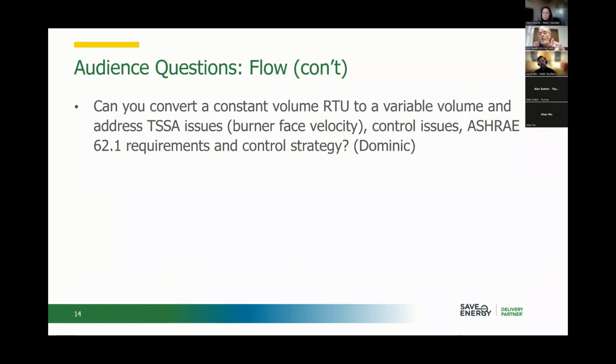There is one point I want to make with this, and that is that you run into a bit of an issue where if you're looking at how much air you need to move in from purely a temperature perspective, that's one thing. But the other thing you have to keep in mind, and this is the issue with any kind of ventilation where it's occupants that you're trying to make comfortable, is that diffusers are above our head at the ceiling, and that air has to get down to the occupant. And if you start reducing the velocity of that air as it leaves the diffuser, you can run into this issue where the air gets short-circuited.